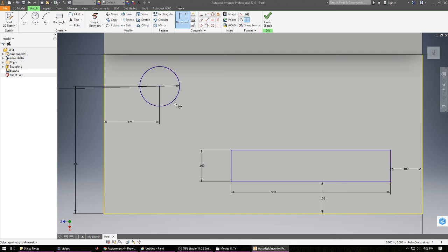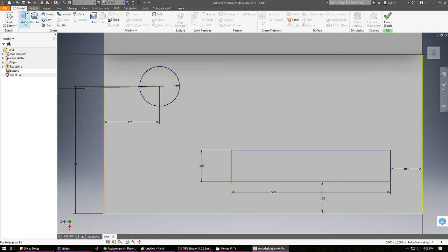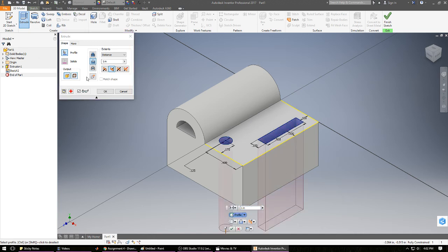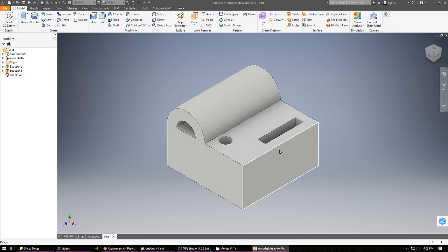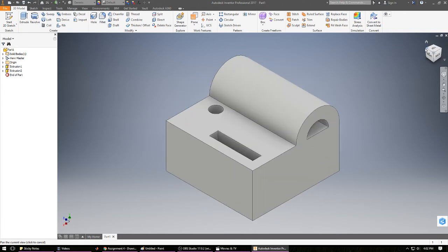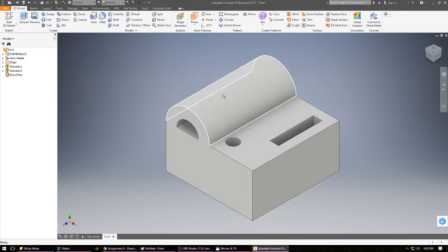Yes? Okay, cool, awesome. And then we're going to extruded cut. And so we're going to select these surfaces that we want to cut. I'm not bothering with the inches because I know it's a through cut. Say this is the part we want. It's kind of ugly, like modern art. It means something. But then we want to show this to our boss with the drafting representation. So this is a part of an assembly that will do lots of wonderful things.